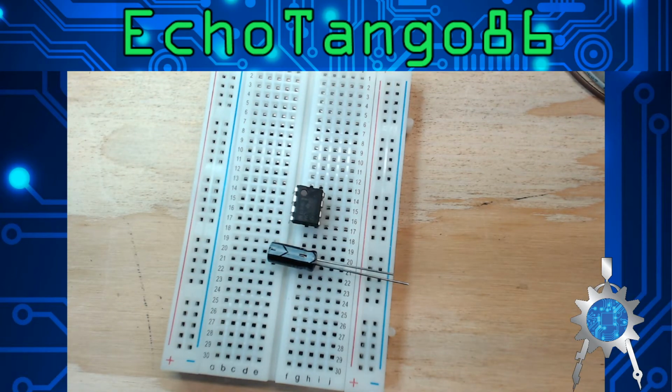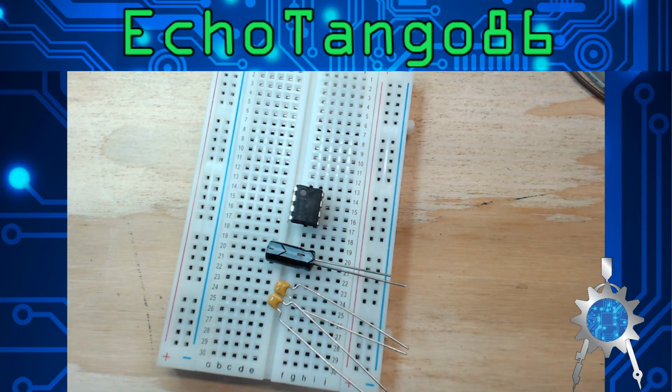Alright, so then what we're going to need is the other capacitors. So we have 2 other capacitors. One goes from pin 1 to pin 8, that's your ground pin and your positive input, and that essentially is just going to allow that capacitor to give you a good constant voltage input, and depending on what you're using as your power source, it will be good to help smooth out anything and eliminate noise. For pin 5, we're going to go ahead and ground that one too, and that one doesn't do anything that we need to really worry about at the moment, but we're going to do another capacitor there to help remove some of the noise that the chip will have. It's recommended in the diagram here from the data sheet.